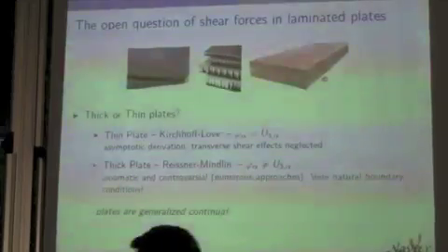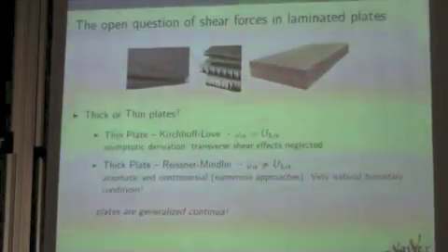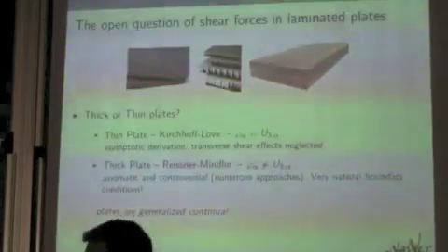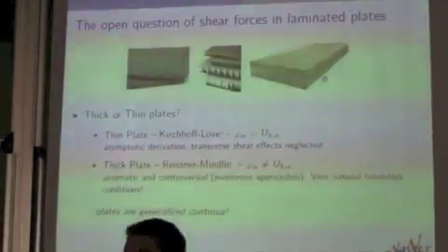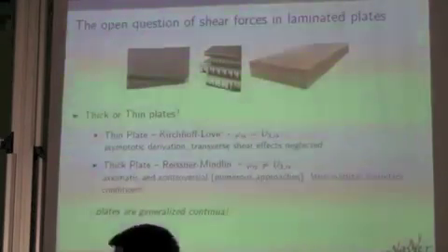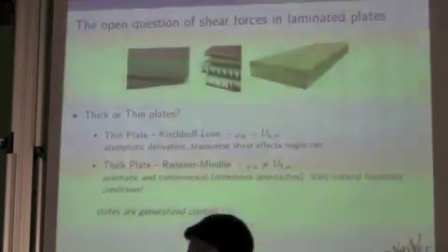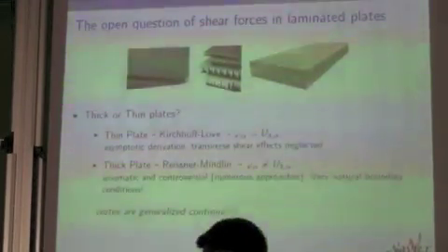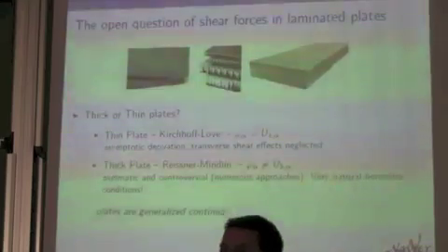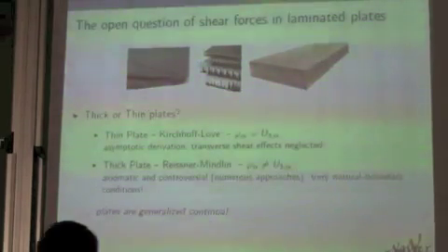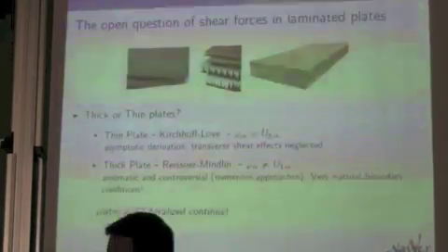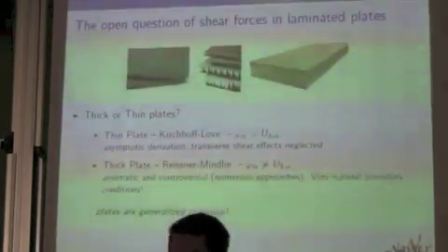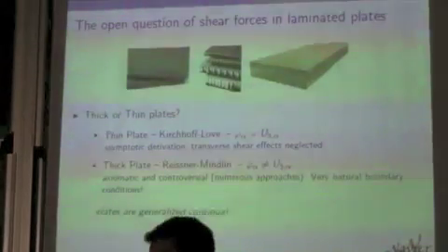In most of these plates, the transverse shear effects are important, and they will fail with transverse shear modes in bending. So if you're an engineer, you will deal with thick or thin plates. If I'm a more theoretical person, the question is: is it a first order plate model or a higher order plate model?